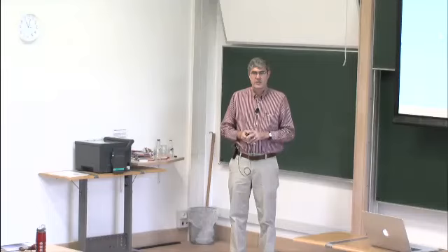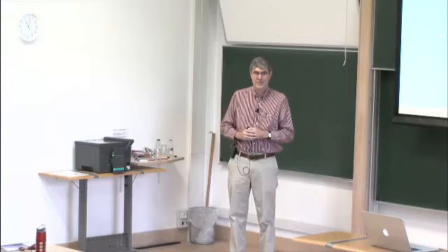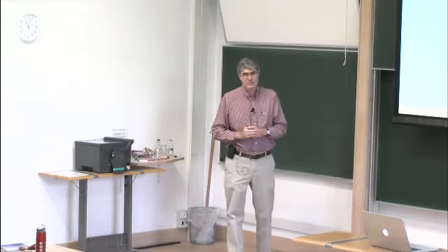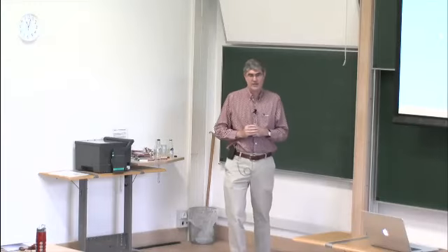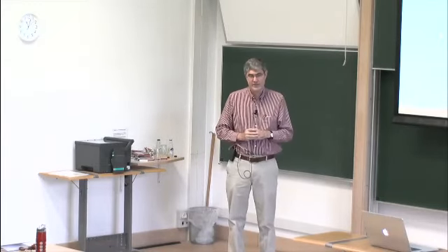So you would also have to do that for the WENO scheme. Then you have more correction terms then. For the WENO scheme, it's written differently. It's not done using that Lax-Wendroff framework. Instead, it's a semi-discrete method together with Runge-Kutta time stepping. So there you are calculating more approximations of what's going on at the interface at an instant in time, and then applying the Runge-Kutta time step. So there you do.